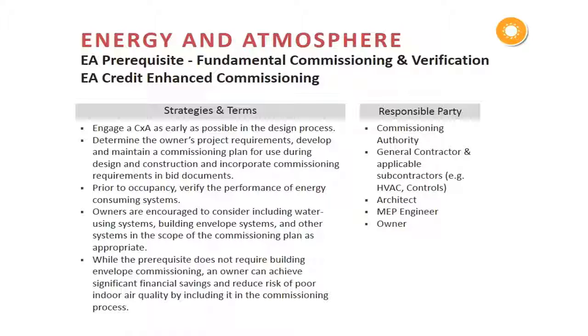The next consideration is the determination of those owner's project requirements and developing and maintaining the commissioning plan so it can be used to inform the design and construction activities related to commissioning, including incorporation of those commissioning requirements into the bid documents. And then make sure that the performance has been verified before occupancy. So testing of these systems needs to happen before the occupants move in.